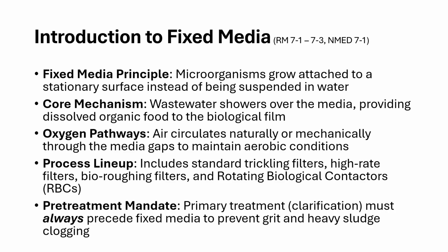And the oxygen, we're providing oxygen because air is circulating between those filter media or surfaces, or mechanically, in the case of rotating biological contactors, we're actually dipping those in and out of a water surface or wastewater surface and exposing them to air. So we're also aerating that waste, if you will, and allowing the biological film to get oxygen to get that aerobic condition, so that we're allowing them to metabolize that waste. Okay, so different perspective. And we are looking at trickling filters.